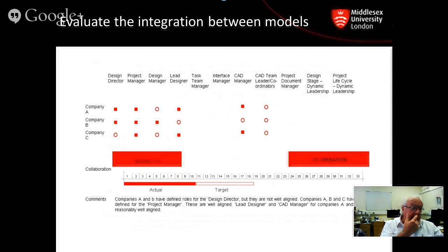Okay. Important set of investigations. Another one before we go on, sorry. Another one from Chema. In my projects, MEP people use millimeters, architectural information people use meters. Are we doing something incorrectly? Yes, you're using different units. This is exactly what I'm saying, Chema. In some respects, using these CPIC documents and going through this kind of exercise, even if people don't want to change for various reasons, and they're usually silly reasons, at least you know what they're doing. You've got that basis, and if you've got that basis, you can plan for it. I'll say this many times: even if people aren't agreeing, if you know what you're disagreeing on, then it can be managed. It's suboptimal, but it is, in my view, still a little step forward in knowing what each other is doing.